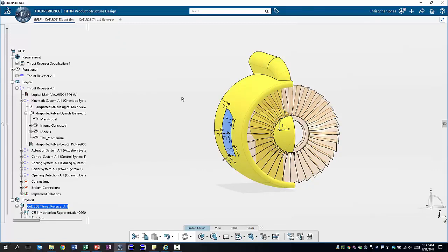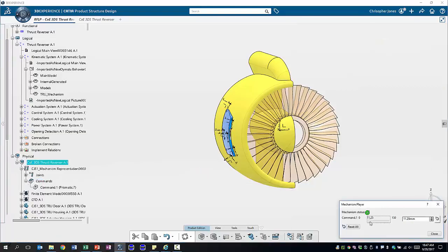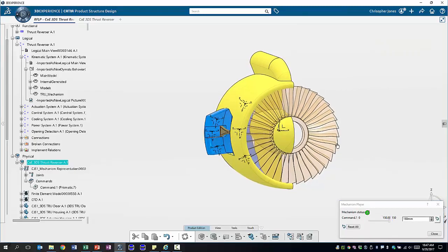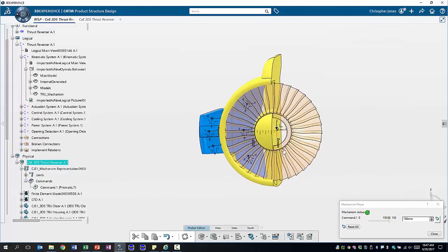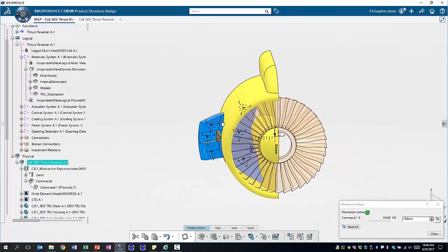We have a model of an engine turbine which has a thrust reverser attached to it. The thrust reverser is nothing but a door in this case that can open and close, and we can see if it's opened, the turbine is, for all intents and purposes, closed, and wind would have to escape out through the door. Clearly, if we open the thrust reverser door, loads onto the door will be significant. We have 6 points on the surface of the door for which we want to determine the load on our system.